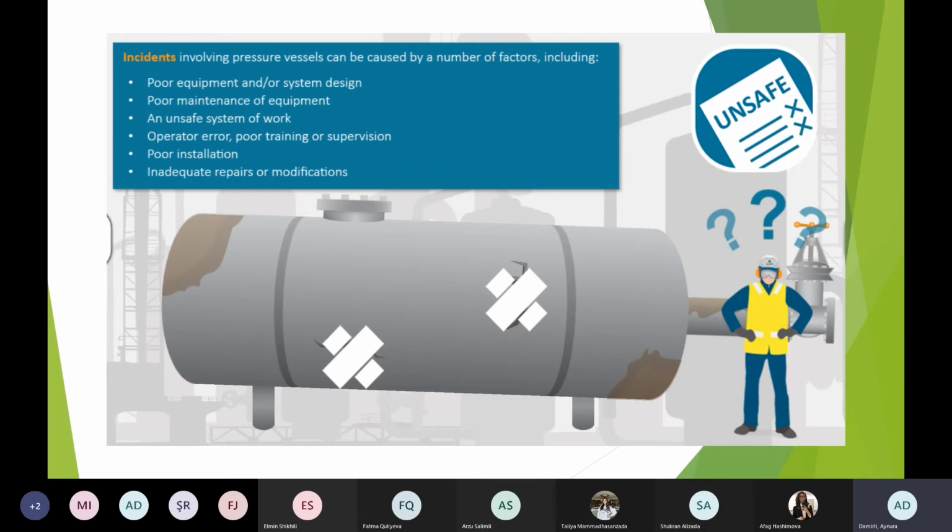And if operators cannot predict that, for example, this design pressure, say we put 50 bar as operating pressure for the equipment, but it increases to 80, and the operator or control room technician cannot predict this on time, this leads to an incident, even if the material, like metal wall thickness, is in good condition, but pressure is increasing by wrong supervision.